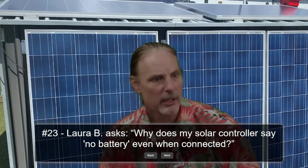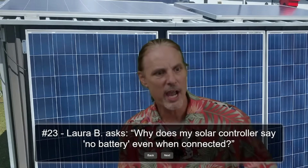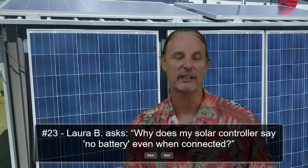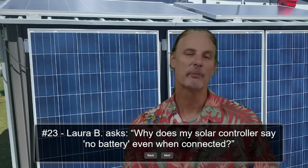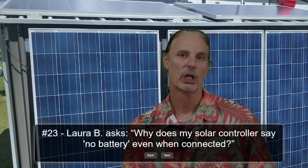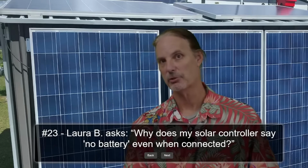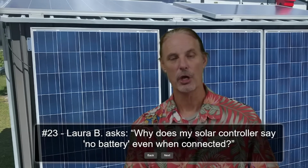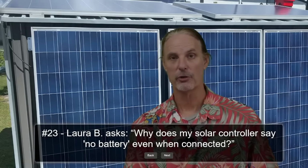Number 23, Laura B asked, why does my solar controller say no battery even when it is connected? Chances are you probably have it set for closed loop, meaning that you're supposed to have communication cables connected from your inverter to your battery.